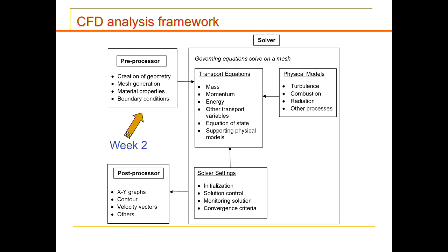That's why we have to monitor the solution, and then determine whether the solution is good enough, or how the convergence is determined by what you set out in your mesh. So everything is linked. It all links back to your meshing and also what results you get at the end of the day. We hope that we can impart this knowledge in the second half of this course.